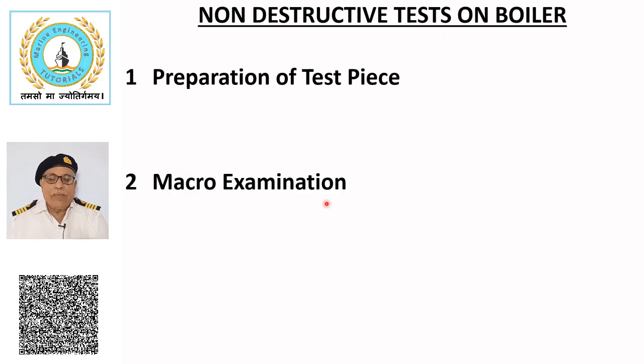Macro examination. The specimen is examined for cracks, porosity, weld structure and heating effects under a magnifying glass of power 10 times magnification. Micro examination.